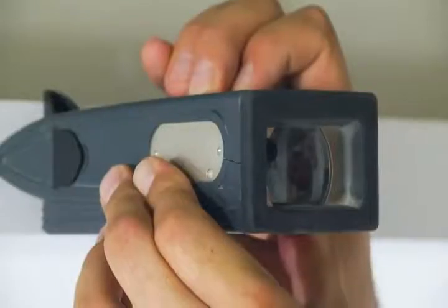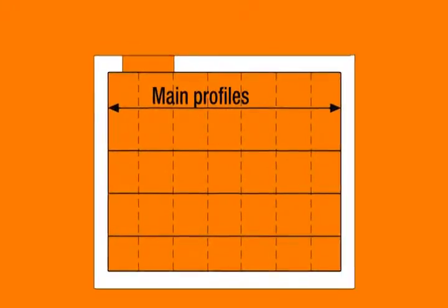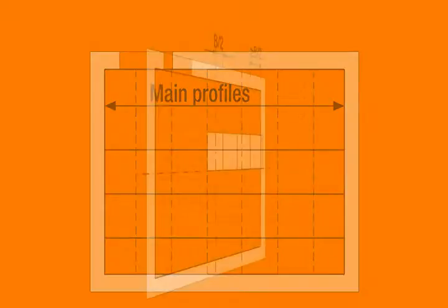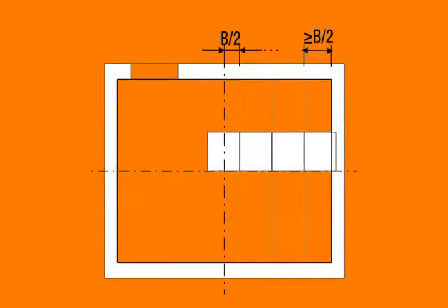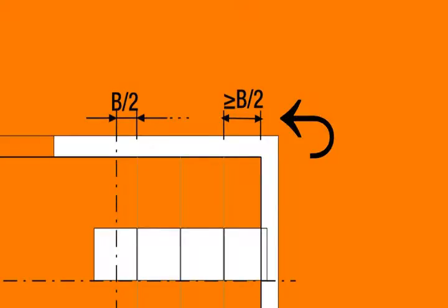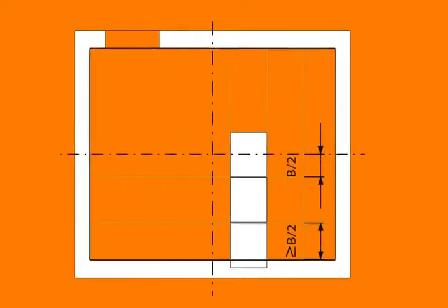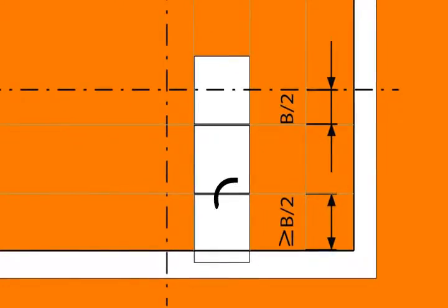After the room has been measured, the reflected ceiling plan and thus the visual layout of the ceiling must be decided upon. Starting from the middle of the room, the layout continues in modules depending on the size of the tiles. Please ensure that none of the cut tiles are smaller than half the tile width or length, as the resulting appearance is aesthetically unpleasing. Starting with the layout in the long direction, the layout continues in cross direction, also in modules.